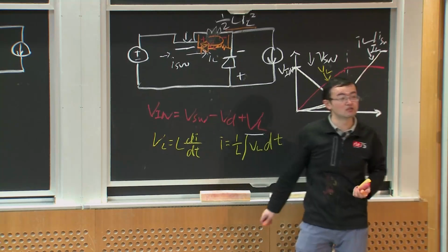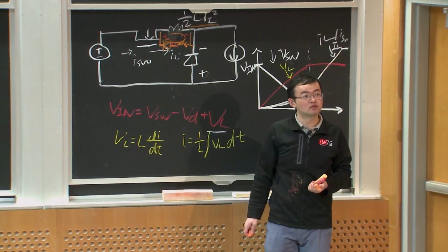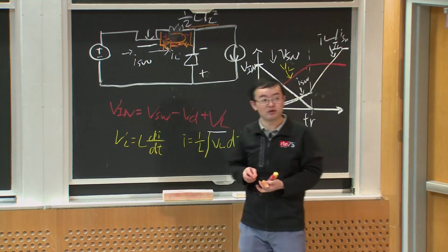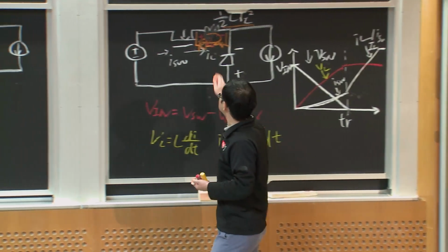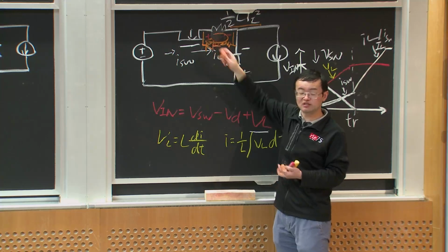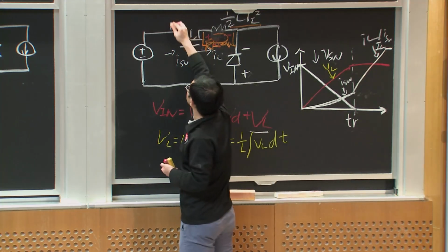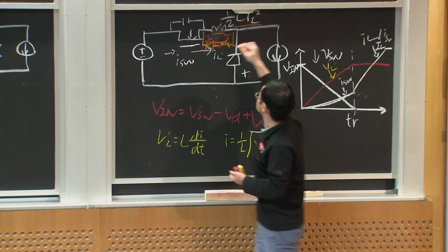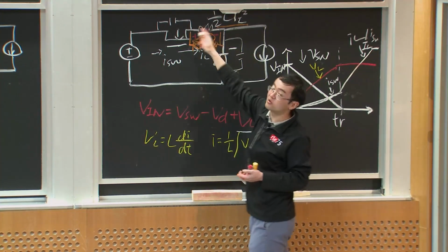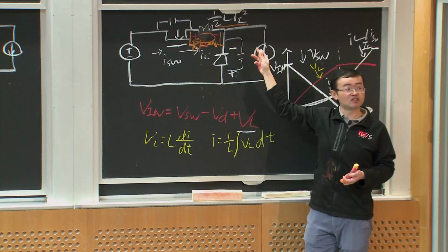Yeah, go ahead. Does adding the capacitor or inductor make the resonance problem worse? Yeah, that's actually a very good question. Because we have a series inductance here, and during some transient we still have this parallel capacitance, and for this diode there could also be some parallel capacitance, they can still resonate. That is something we cannot avoid.